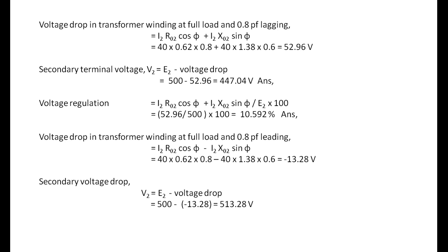What we are observing here is, when the power factor is leading, it is giving out reactive power, so the available voltage across the load is greater than the generated voltage. That is why, with a leading power factor, the terminal voltage is greater than the induced voltage. Therefore, we are getting negative regulation, unlike when calculating the regulation at lagging power factor.